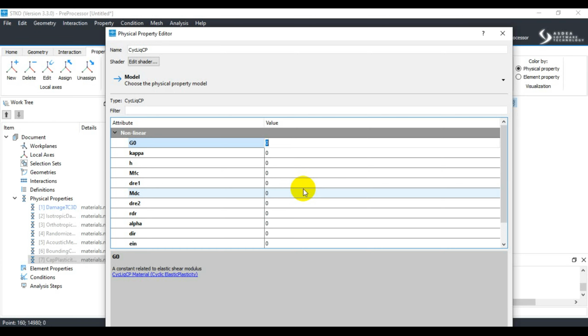When used with regular solid elements like four-node quad or brick elements, the model simulates the response of drained soil, which means soil where water can flow freely. And when coupled with soil-fluid elements like UP elements and SSP UP elements, it can simulate undrained and partially drained soil behavior, which means it can model situations where water flow is restricted or only partially allowed.